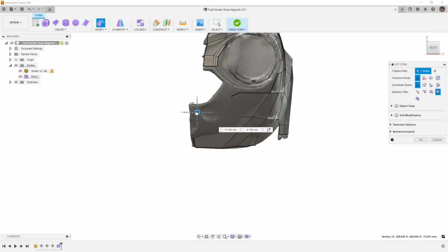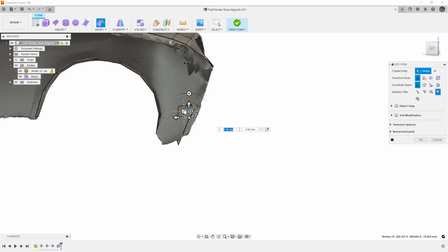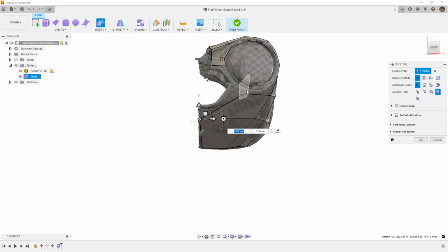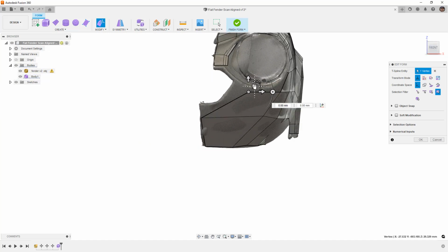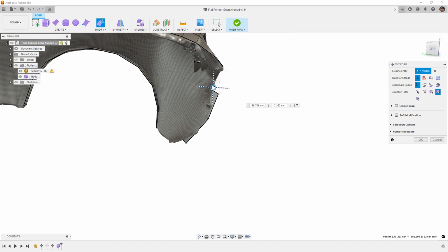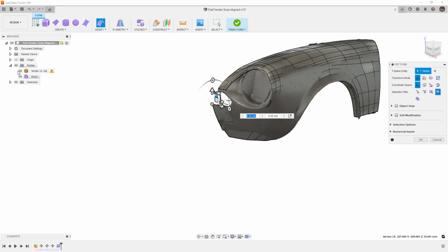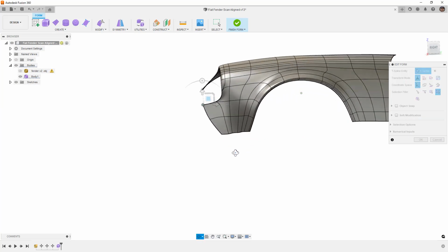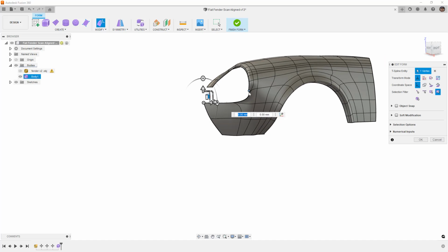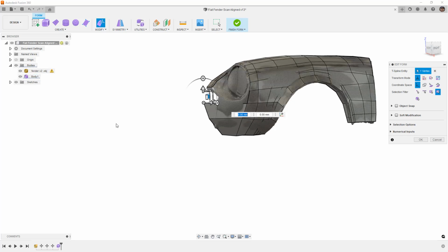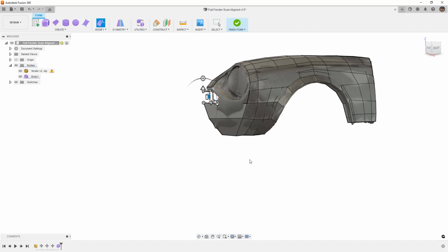From the side, I'm going to pull this over, rotate it around, pull it forward. And all I'm looking to do is get this kind of close, and then we can divide it up. So I'm going to pull that over, pull it forward. And let's take a look at it in smooth, hide this. And you can see what we're doing is we're starting to wrap that around. We're going to start dividing it up, and then we're going to add more edges here so that we can start to move that star point away. So back in box display, show the mesh. Actually, I'm going to say OK and save this just to make sure that we're not losing any work.